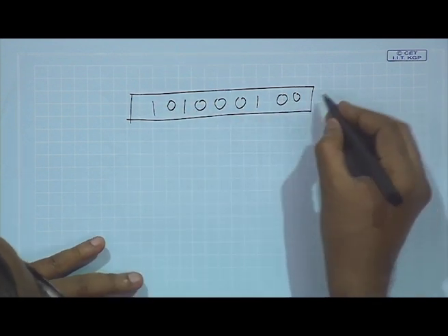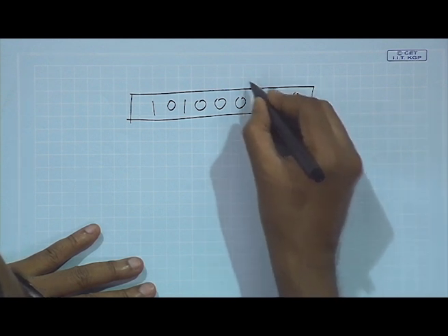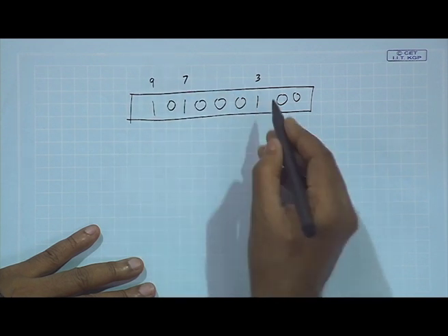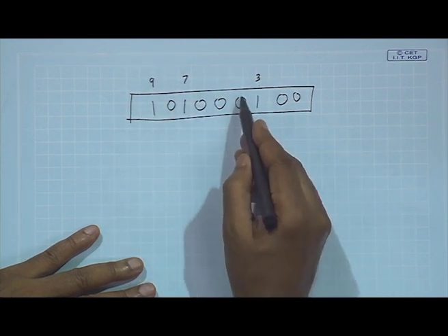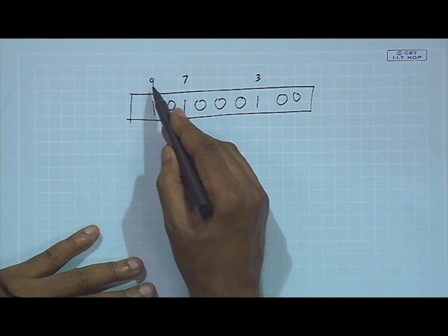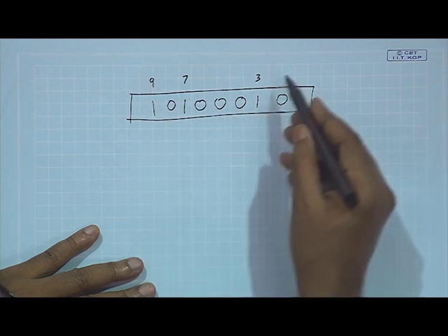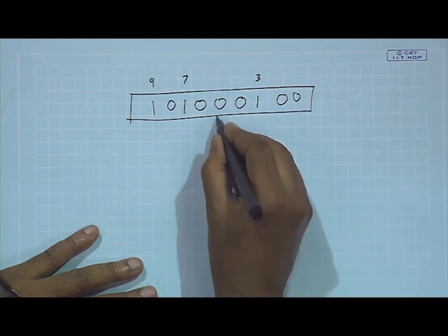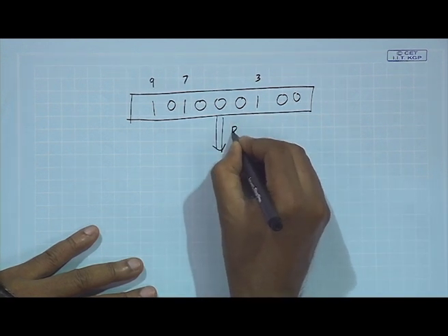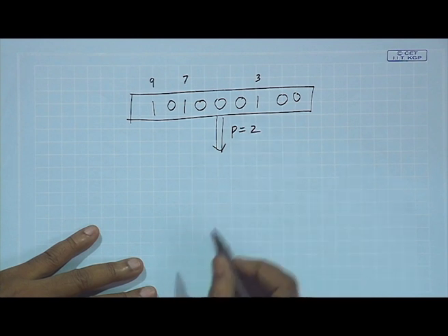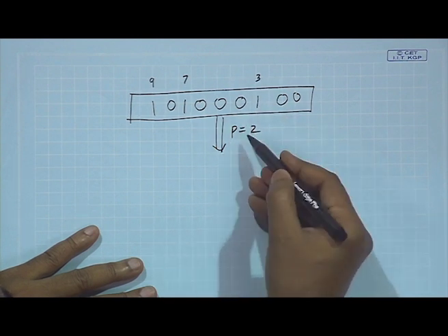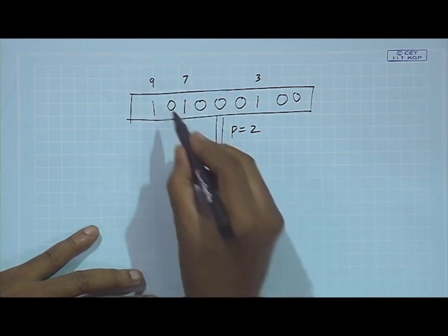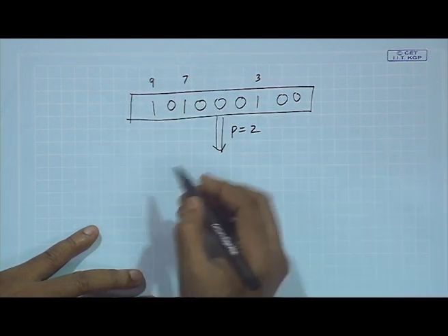Which means that from time 1, 2, 3, 4, 5, 6, 7, 8 and 9, times 3, 7 and 9 are my forbidden times where I cannot feed the next input. These are forbidden latencies. But now say if I advance my time by 2 steps, then whatever was 3 now, after 2 steps will become 1, 7 will become 5, 9 will become 7. So, actually we are shifting this right by 2 positions.